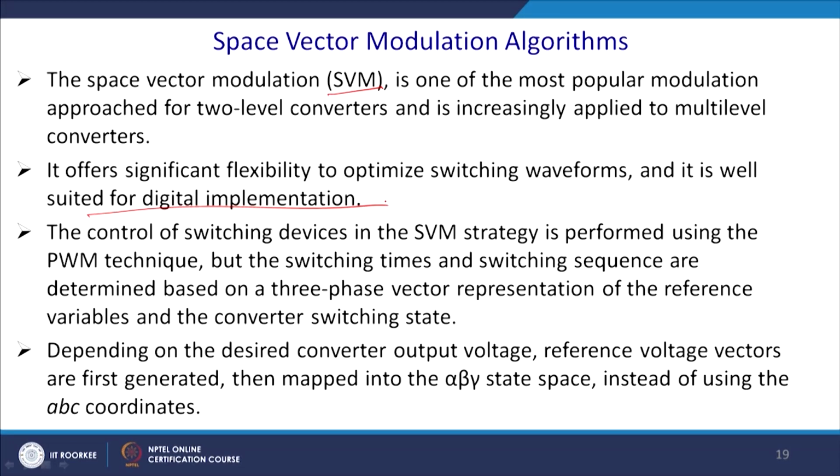The control of the switching devices in the space vector modulation strategy is performed using the PWM technique, but the switching times and the switching sequence are determined based on the 3-phase vector representation of the reference variables and the vector switching states.